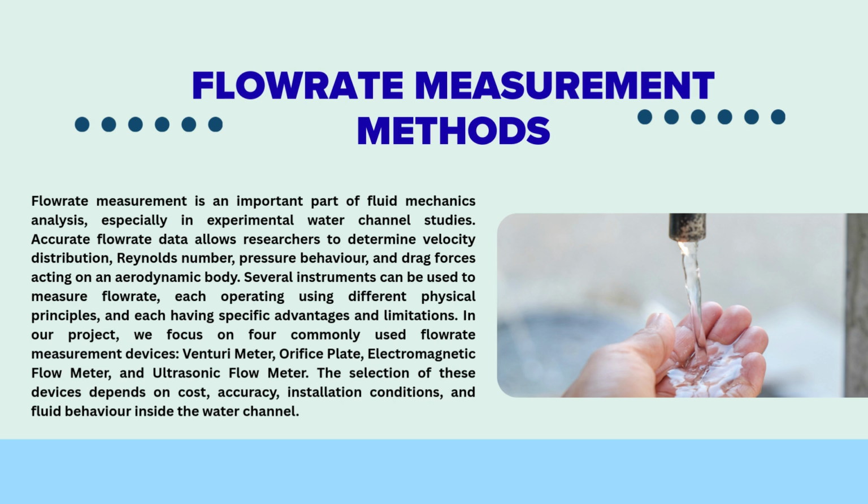In our project, we focus on 4 commonly used flow rate measurement devices, which are the venturi meter, orifice plate, electromagnetic flow meter, and ultrasonic flow meter. The selection of these devices depends on cost, accuracy, installation condition, and fluid behavior inside the water channel.